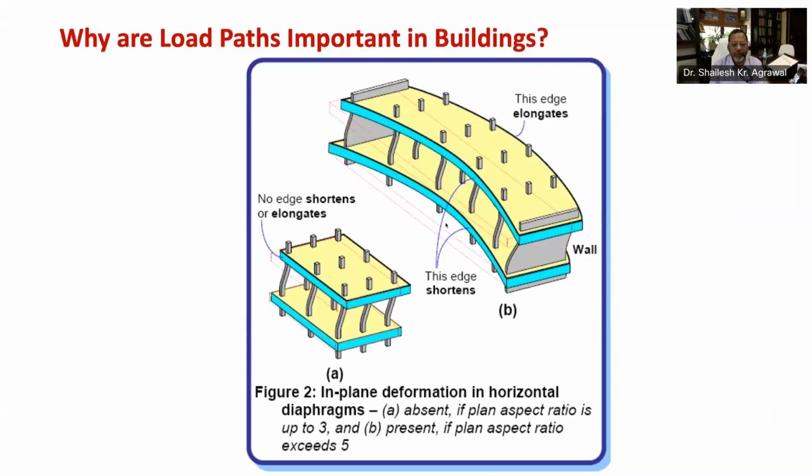vertical elements. Openings in floors are necessary, such as to allow elevator or lift core or staircases to pass through. However, these should be as small as possible and as few as possible. Also, their locations should be carefully considered. The ideal location for openings is close to the center of the floor slab in plan.